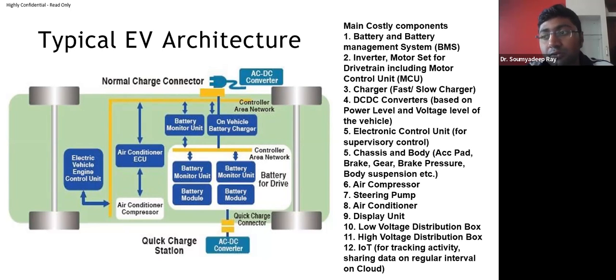This kind of standards will give you the confidence, because suppose anybody is doing power quality things and harmonic mitigation things, and they say, okay, my harmonic should be less than 5%, but who said that? I am not saying it, or anybody else. It is said by the IEEE 519 standard. You need to clearly mention who is saying this standard, so that you are confident that your result is getting validated. Okay, so you need to be within that boundary.